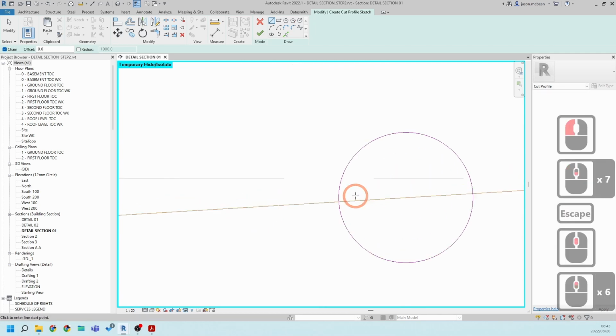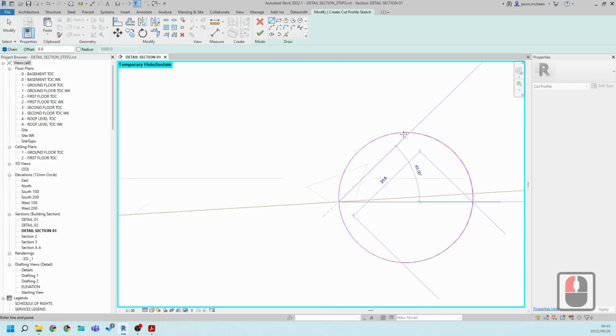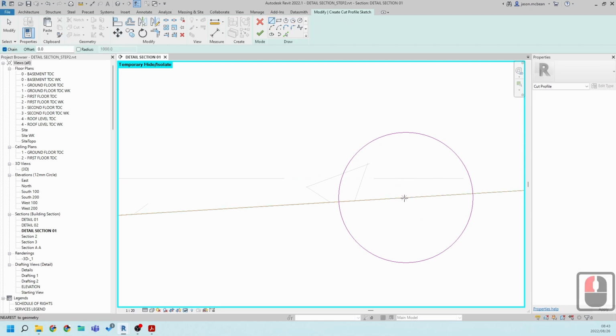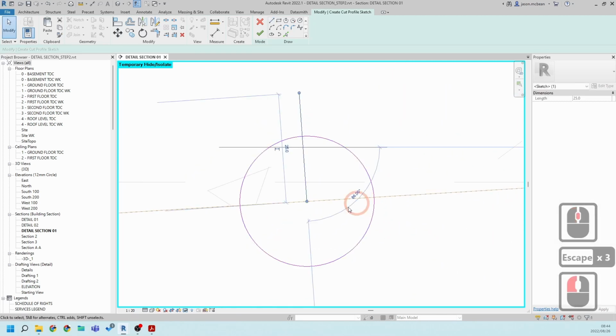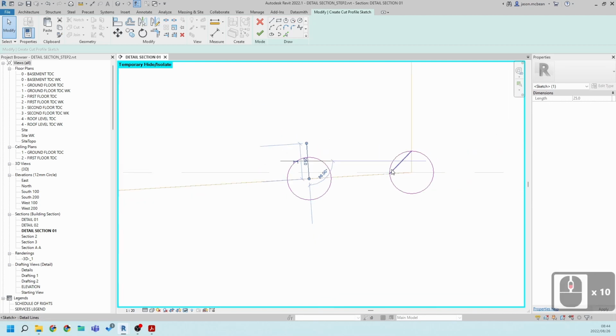And then here I'm going to draw my line tool. This is different, so you're going to create another line tool. Snap center, and then you want this perpendicular to this line over here. You can see this is problematic sometimes, so you want to change which line this uses.